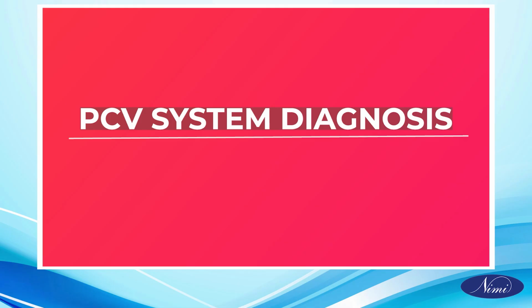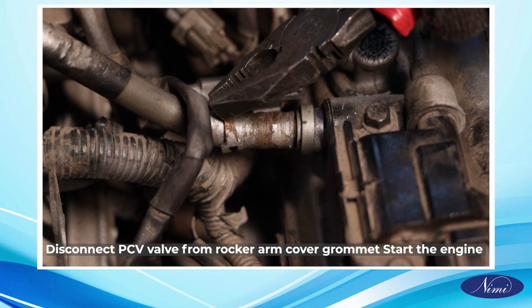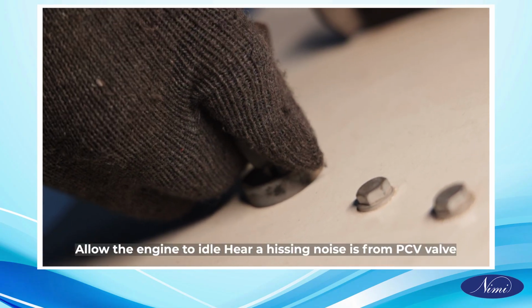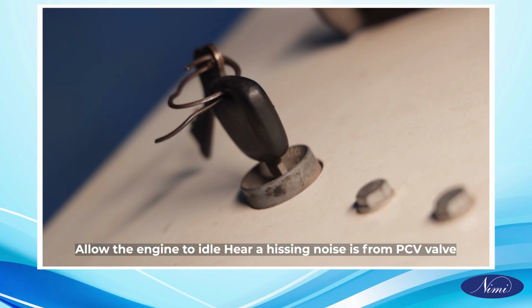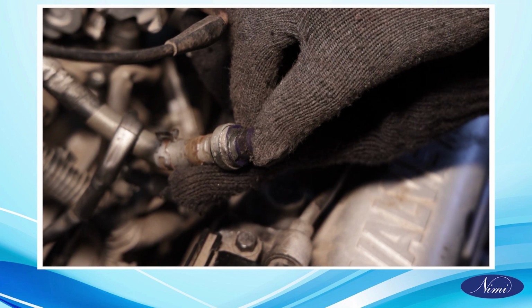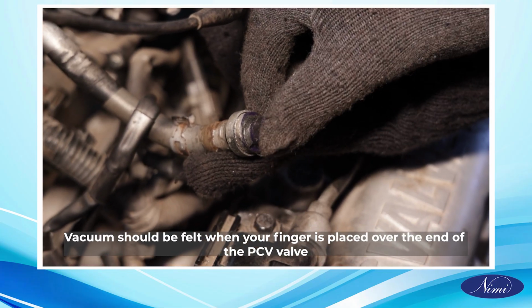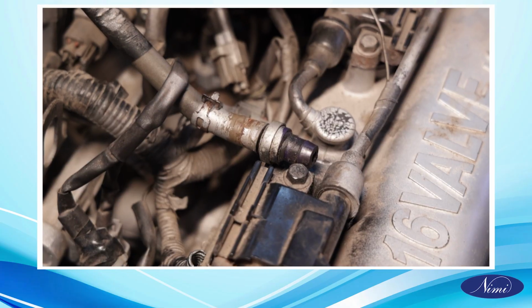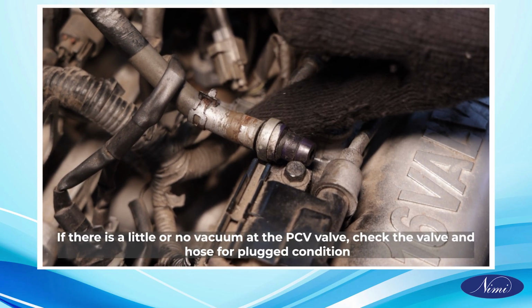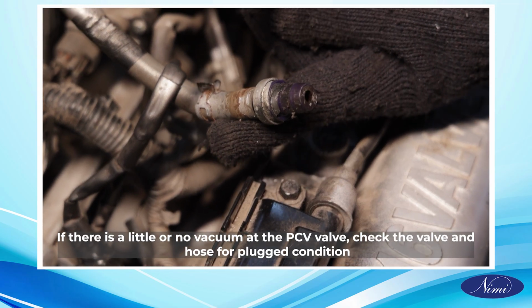PCV system diagnosis. Disconnect the PCV valve from the rocker arm cover grommet. Start the engine. Allow the engine to idle. Here, a hissing noise is heard from the PCV valve. Vacuum should be felt when your finger is placed over the end of the PCV valve. If there is little or no vacuum at the PCV valve, check the valve and hose for a plugged condition.